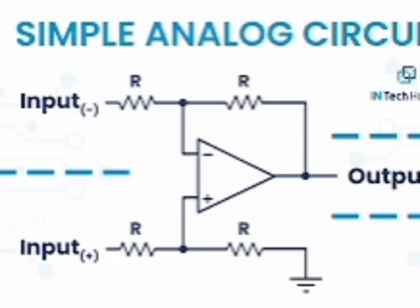Common collector amplifier or emitter follower. DC output voltage Vout equals Vin minus VBE. Input impedance Zin equals R1 parallel with R2 parallel with beta RE. Input impedance seen from base, Zin base equals beta of RE plus RE dash, equal to beta RE. Output impedance Zout equals RE dash plus numerator part RS parallel with R1 parallel with R2, denominator part beta, that is RE dash plus RS parallel with R1 parallel with R2 by beta.